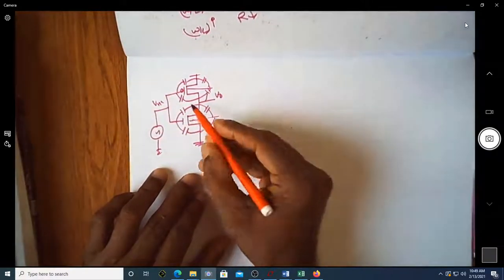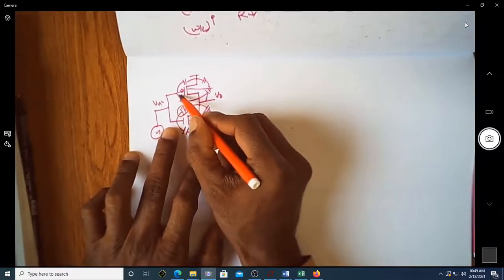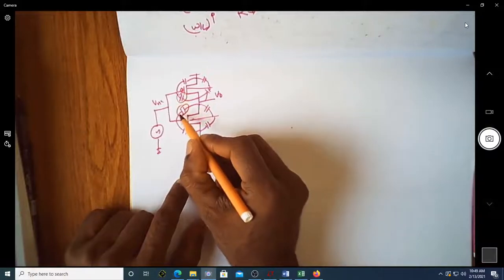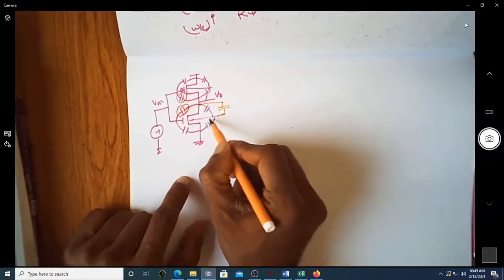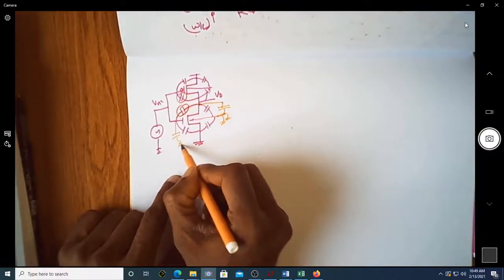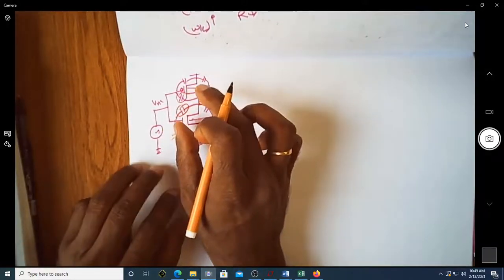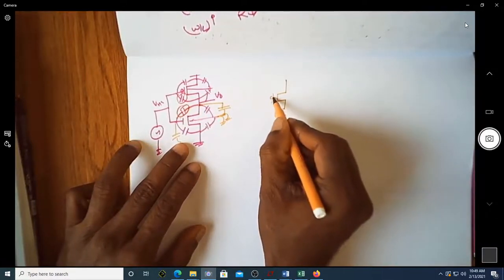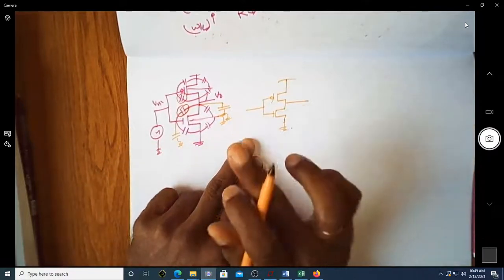Of course, we know that there is a capacitance existing between output and input, which is CGD of NMOS. Again, there is one CGD of PMOS transistor. Using Miller's theorem, we can split this floating capacitance into a capacitance from drain to ground, which is also usually grounded, and again one from gate to ground. So this is the actual capacitance that you want to end up with. I can represent the entire inverter by only two capacitances.